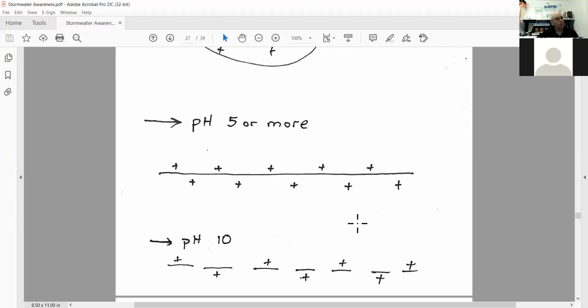What is the difference between a coagulant and a flocculant? That was asked for a couple of weeks ago. A coagulant is a substance that causes particles to clot or bind together. Typically, this is done using a coagulant of opposite charge of the target particle, like in our case, cationic polymers attacking anionic particles. The flocculant is a substance added to a suspension of coagulated particles to form larger particles that can gravity settle or be removed in filtration. That is a big difference between a coagulant and a flocculant.